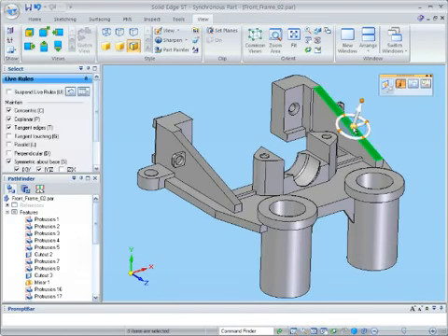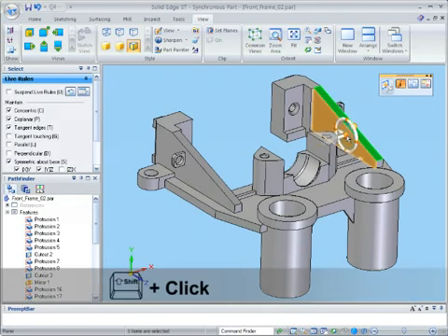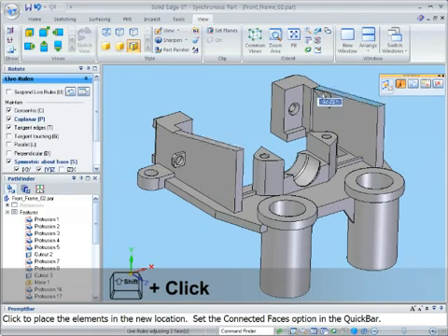To rotate a face, select the face to be rotated, then reposition the steering wheel by dragging the origin so that the torus is perpendicular to the face. You can see that the steering wheel snaps into key points and reorientates automatically. By shift-clicking on the origin and then dragging the steering wheel, its orientation is preserved.